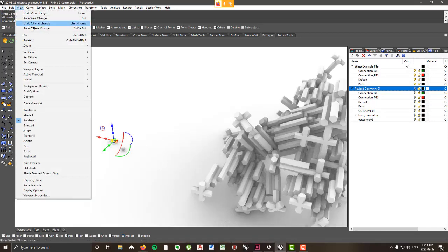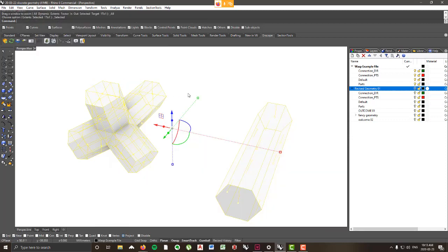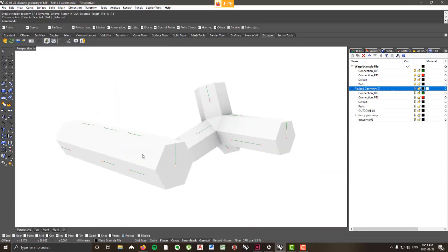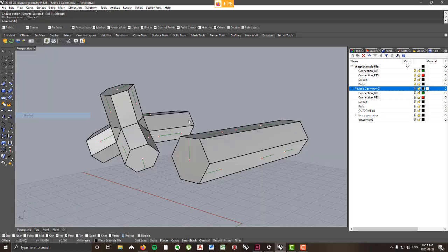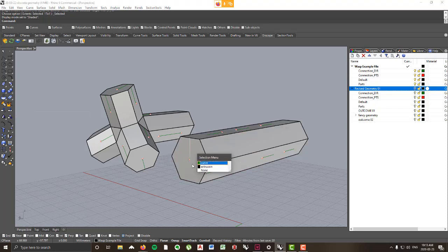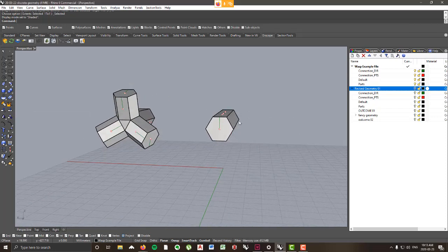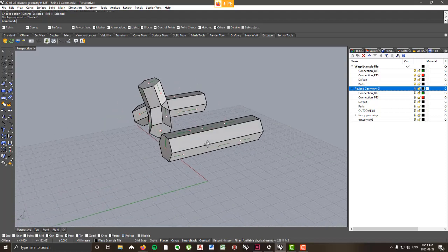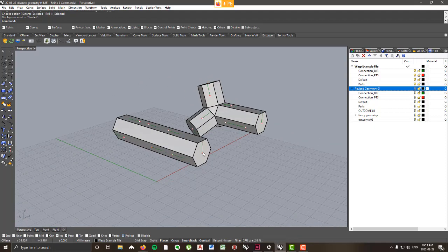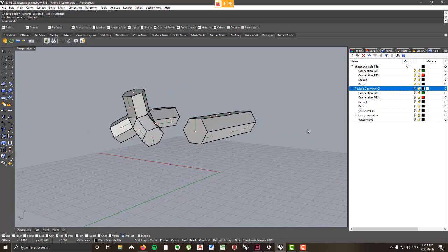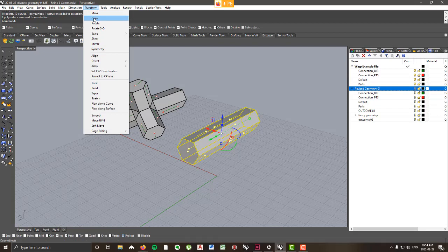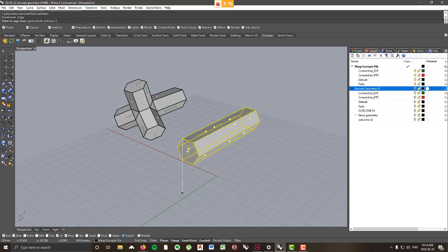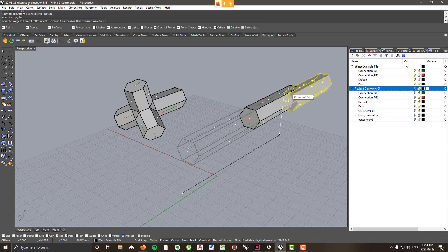Here, I'm just going to zoom in. Connect this linear piece to itself based on predefined rules. The way Wasp works is that it uses curves and center points to create connections. So for instance, one connection we could define is connect this point to this point, and make sure that these lines are oriented in the same direction. If we define that rule and said we wanted 3 pieces in that aggregation, we would have 1, 2, 3.